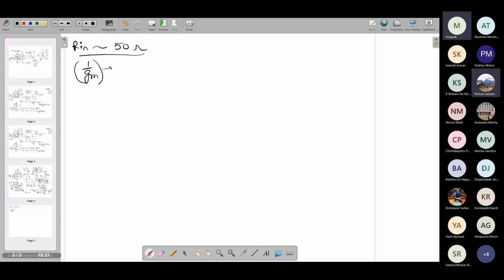So there are other techniques like feedback, with the help of which in this particular circuit we can achieve much lower impedance, and these are used in many applications, especially high-speed communication circuits. There are two extremes for this kind of circuit. One extreme is where the input signal strength may be large, but the bandwidth required is also very big. That means a communication circuit, for example.